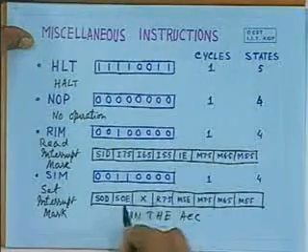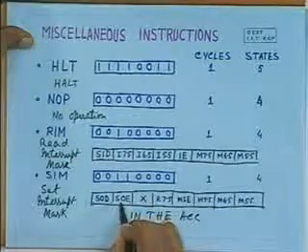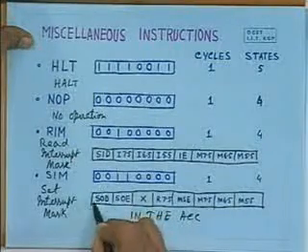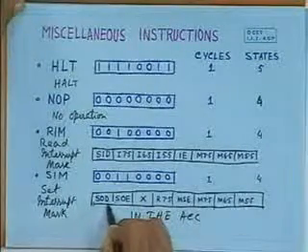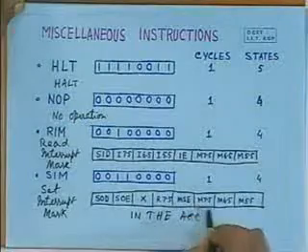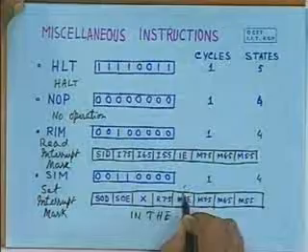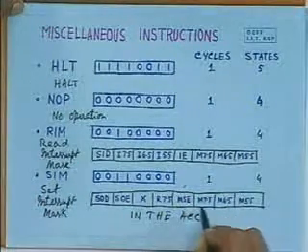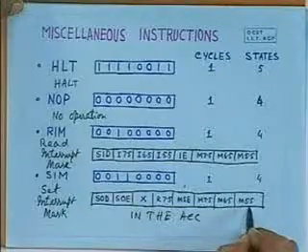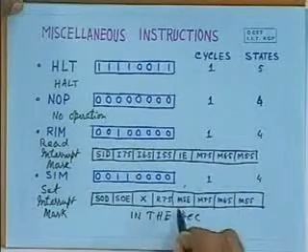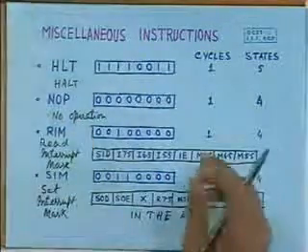And it is a dual purpose instruction. With the help of serial output enable, you can transfer some data on the output line, the SOD line, and also you can set the mask bits by putting this bit here. That means whenever this mask set enable bit is 1, you can set the mask bits 7.5, 6.5, 5.5, and accordingly the various interrupts will be masked.